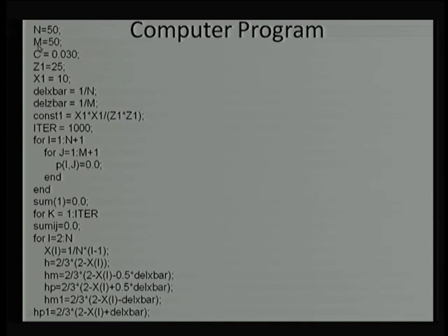Similarly, in the z direction again we are taking the number of nodes as 50. As I mentioned, we are assuming equal spacing in the z direction and equal spacing in the x direction. So, that term has been simplified in the equation. This C is the clearance. We are assuming, for the example which we have been quoting for the different kinds of approaches, a radial clearance of 30 micron which we picked up, and here we are also keeping the same thing. We are keeping 30 micron as the clearance, but for different examples where C is different, we can use that different value.